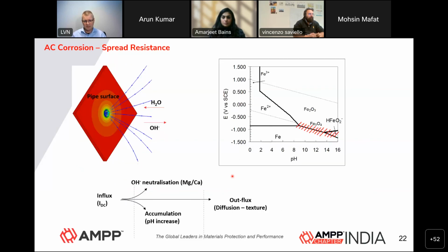But if you have magnesium or calcium in the soil, instead of creating a lower spread resistance, you can also have an increased spread resistance, and thereby the whole situation comes into balance again. So yes, the environment has a very high effect on whether you get AC corrosion or not. But it's very difficult to tell in advance which kind of environment does not create AC corrosion, in my experience. Okay, thank you. Mitigation for you is also related to the use of earthing electrodes through polarization cells or overvoltage diverters,